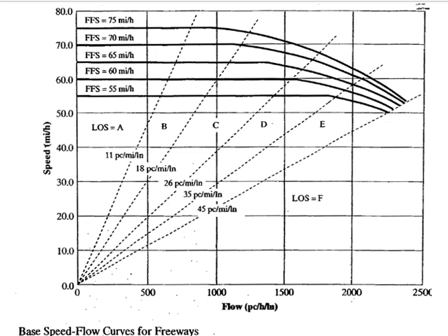Okay. I told you earlier, this method of calculating level of service comes from the Highway Capacity Manual. The manual has a fixed density for each level of service. There is a range of density which is fixed for each level of service. For each type of highway the range could be different, but it's the same. The other things are different, so the graph will be different, but the range is the same.